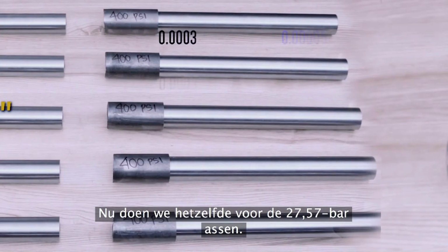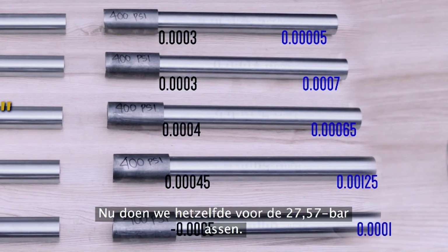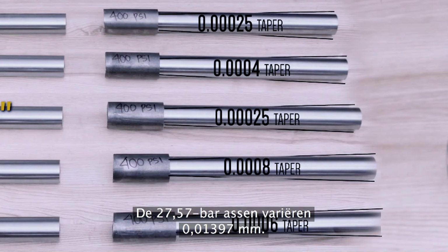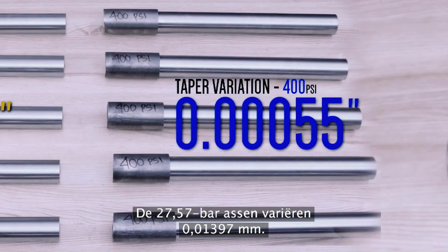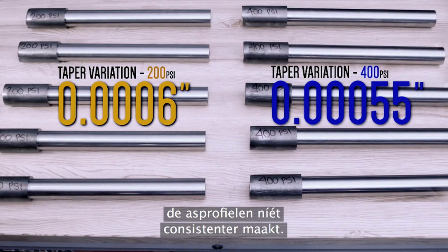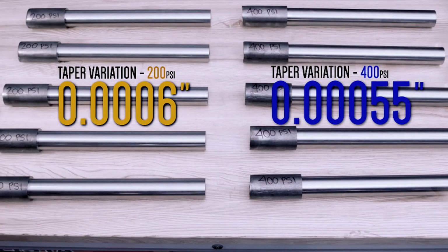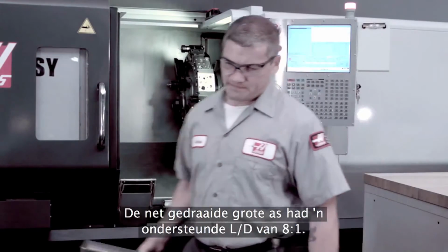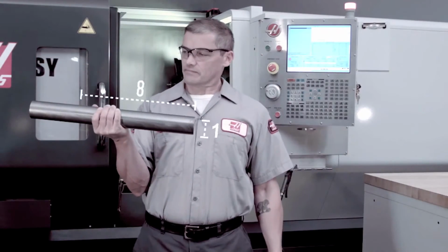Now let's do the same thing for the 400 psi shafts. We find the taper for each shaft and compare these values. The 400 psi shafts vary by 5.5/10. Maybe this seems surprising, but we can clearly see that more tailstock pressure did not make the shaft profiles any more consistent. The large shaft that we just cut had a supported L/D of 8:1.